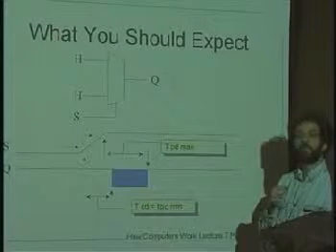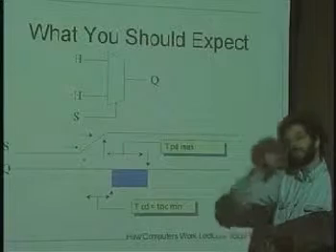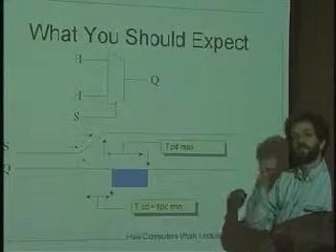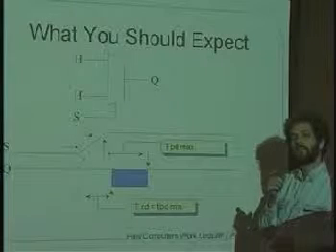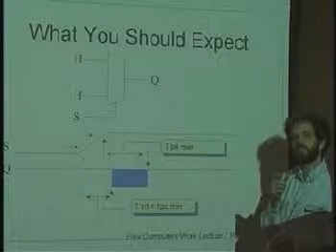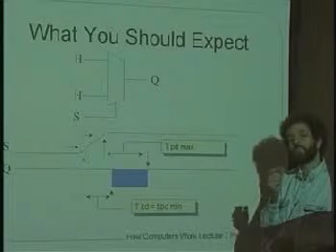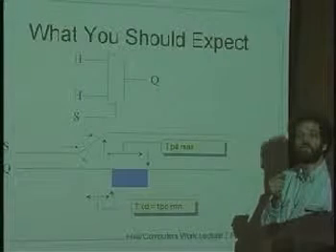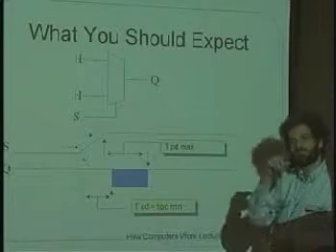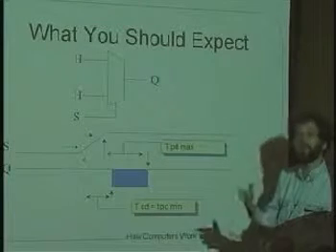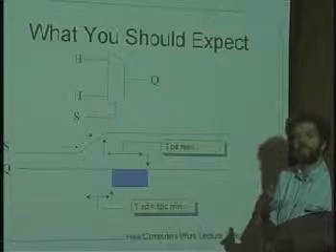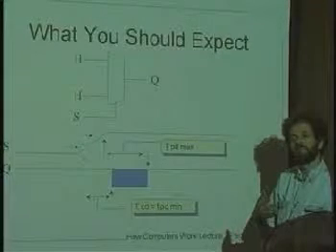too fast. Do you remember the hold time thing, right? We don't want the contamination to race around the loop before the hold time is up. So circuit designers in general worry about, will the contamination get to me too soon? And so the question is, what's the smallest amount of time for the contamination to start to race around the loop? One could say, what is the maximum amount of time too? One could measure that. But in general, it's not a measure that's very useful.